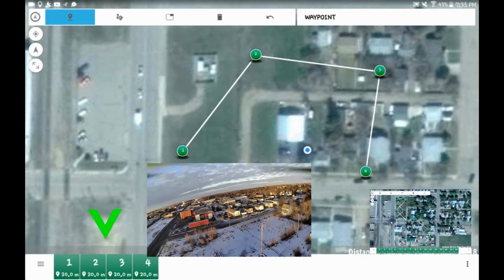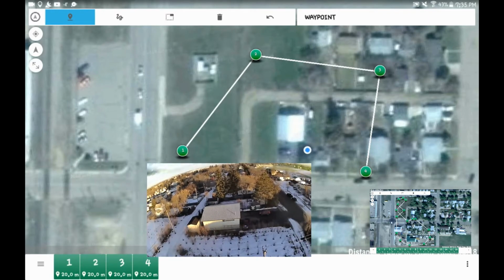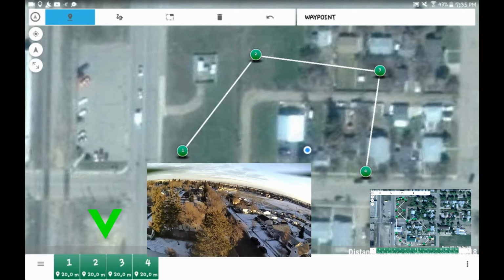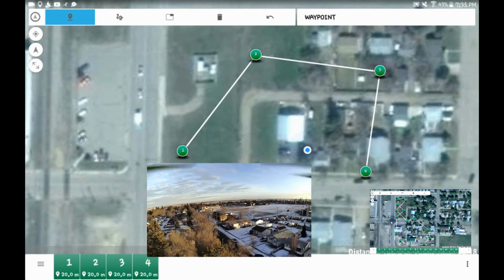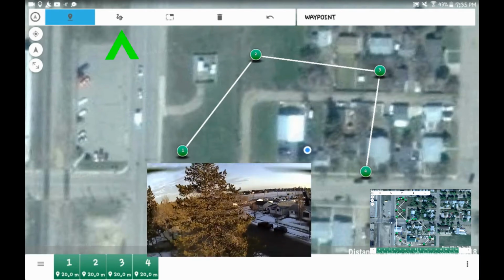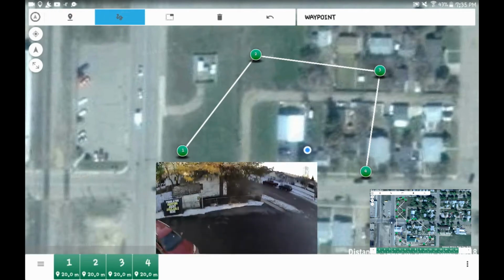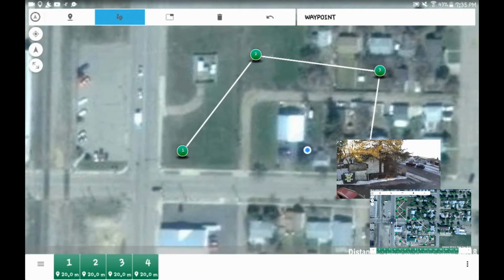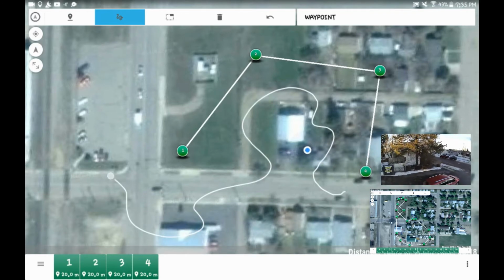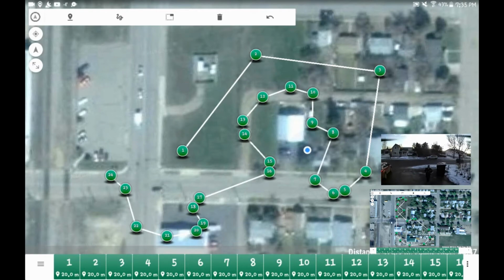If you look at the bottom of the screen, it added the little waypoints, 1 to 4. They show the waypoint at 20 meters, which means your drone will fly to 20 meters at waypoint 1, 2, 3, 4. And there's another way to make waypoints. We can click on the next icon beside it, which is the squiggly line icon, and it allows you to draw a cool, intricate pattern through an area, and you can see it added a whole bunch of waypoints. So either way, we'll add waypoints. You can see they're all 20-meter waypoints, 1 through 24. That's how you draw them on the screen.